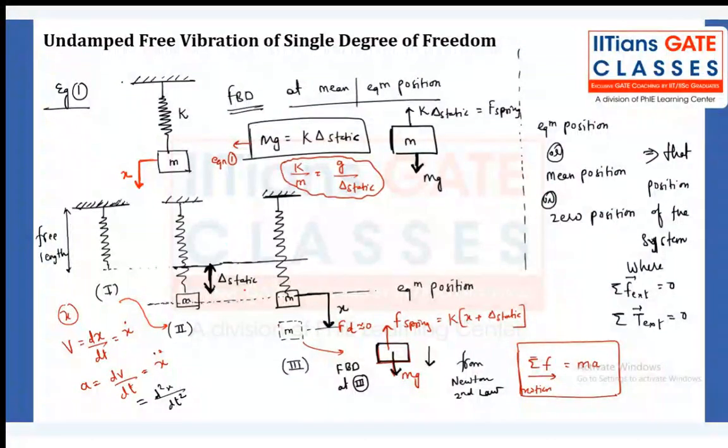After attaining the equilibrium position from the static deflection, after getting deflected statically, we are disturbing it by the amount of x, by the disturbing force Fd. And that disturbing force will run away after some point of time. It is gone. It will not be present in the system. That's why we are calling it free vibration or natural vibration, right?